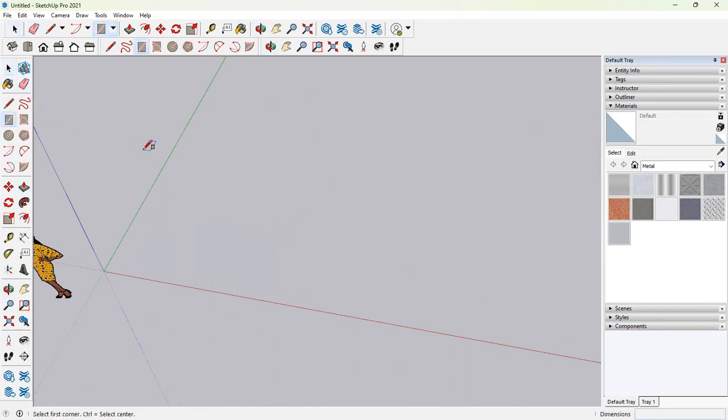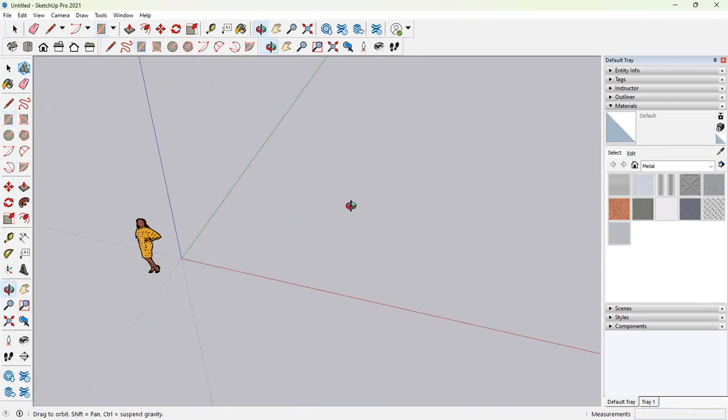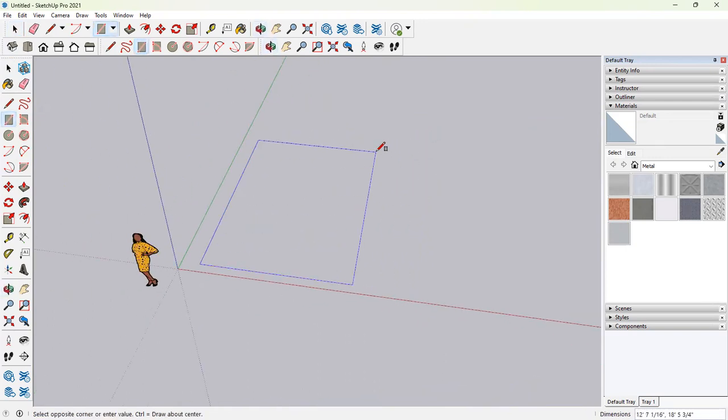the rectangle, or it also gets activated by the key R on your keyboard. And then you can stretch and draw. Now, the similar thing, if you want to draw it on your XY plane, it will be snapping to the blue axis.